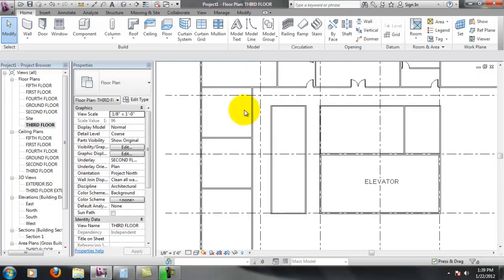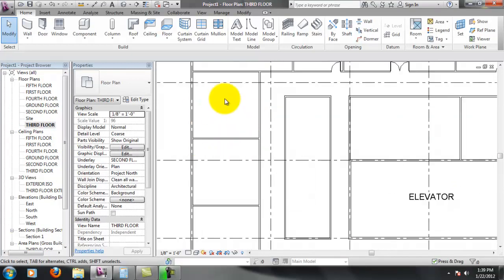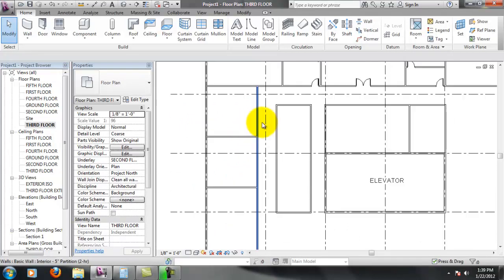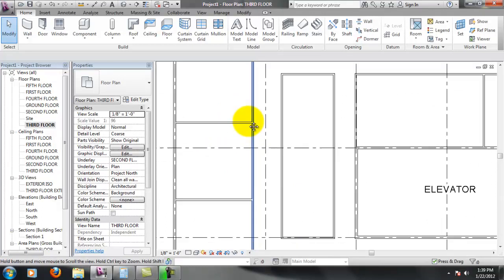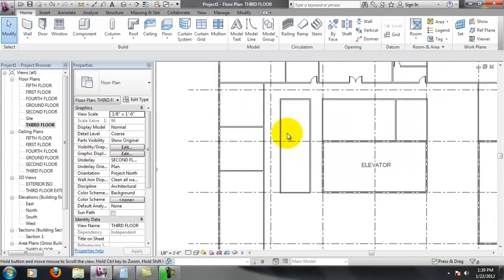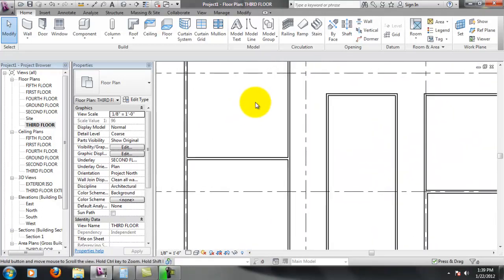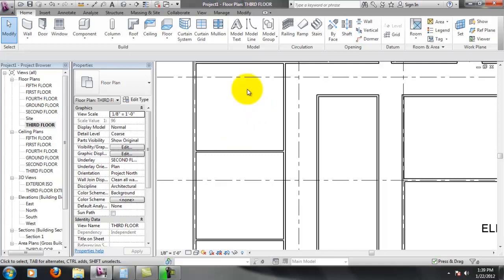And remember, in this area, I was interested in putting the restrooms here originally. So I think it looks like we still have some space to do that. I'm going to go ahead and try and fit both of those restrooms. And remember, we need 5 toilets, and that doesn't necessarily include ADA stalls. I didn't reference the ADA handbook to see how many of those stalls I actually needed. And I imagine we probably need at least 1, if not 2, ADA stalls in this size of a room.